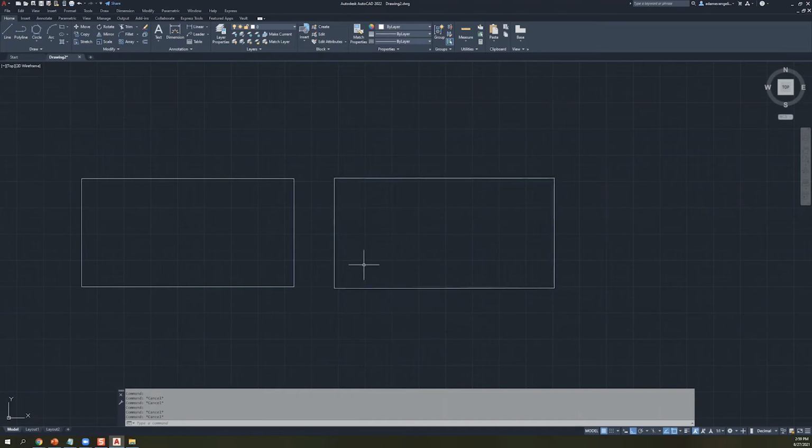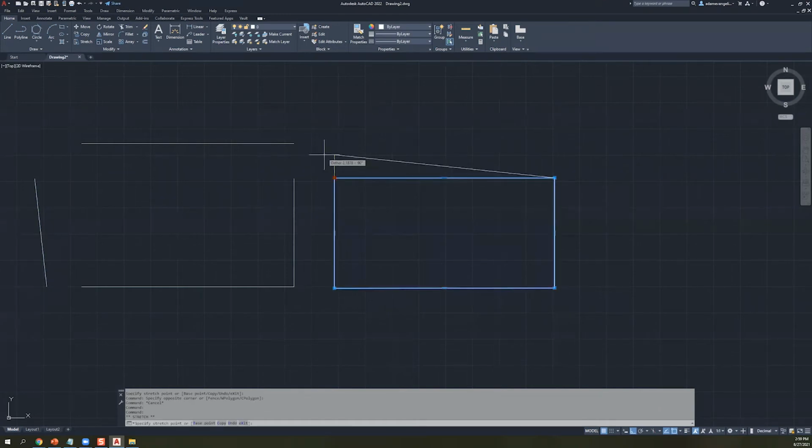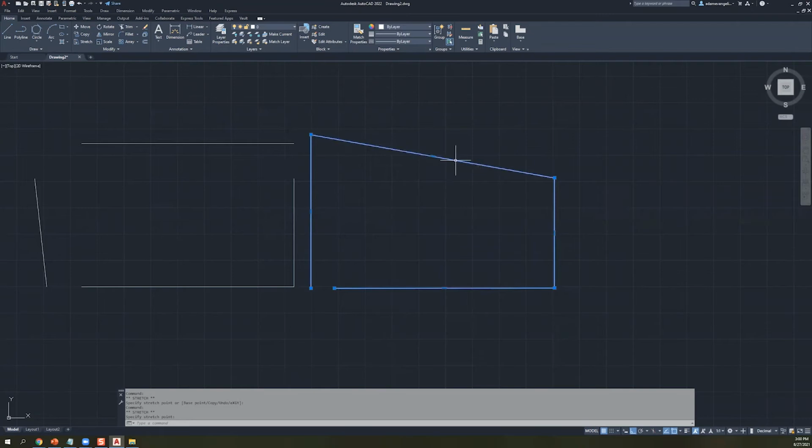But the main difference is that with the regular line object, you're making individual lines that happen to be coincident at the end. When I click and pull all these edges, things change with it. They do try their best, but they're not really connected at the end of the day. They're four individual line objects, whereas a polyline is considered one continuous object while having multiple edges. In fact, this goes a bit further in that you could actually pull and stretch and keep stuff connected depending on what you do over here. This isn't a true close here as well, so that's actually my fault. I didn't make a true rectangle here.